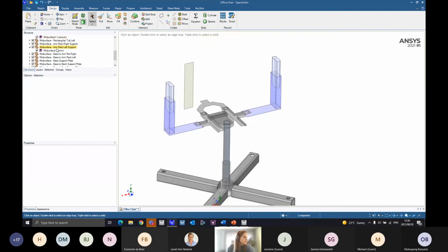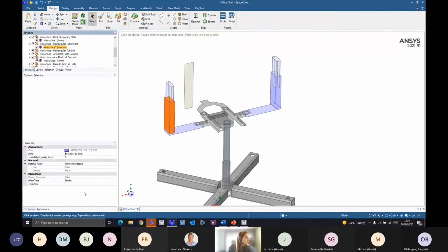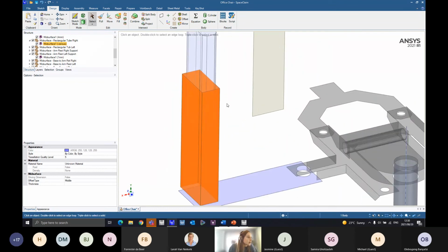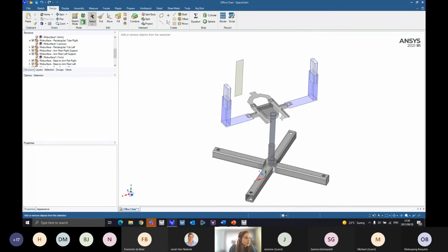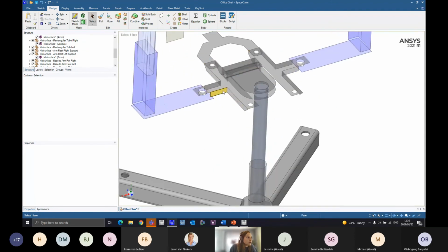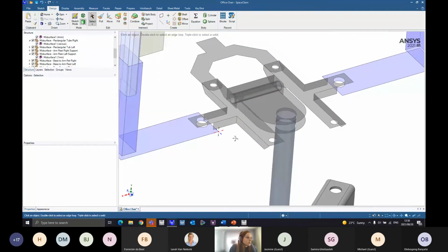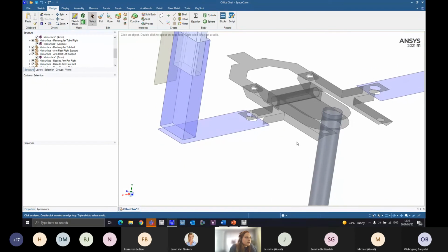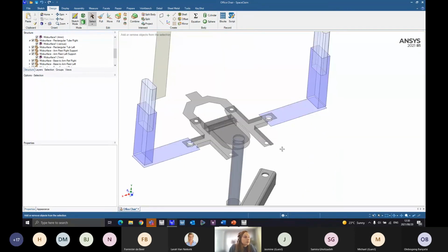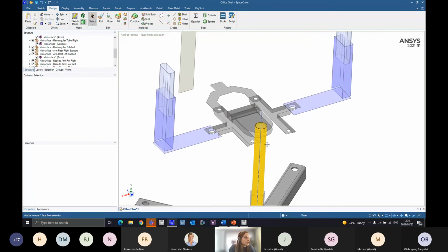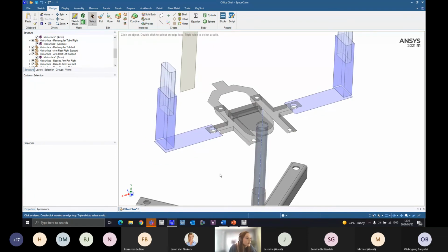I'll investigate that a bit later. Oh, it's just saying various. Okay, that's new. So it's actually capturing the various thicknesses of this body. Okay, then what I would like to do now is just kind of ensure that the mid surfaces that I've now kind of represent the 3D geometry and make sure that they are in contact as well.